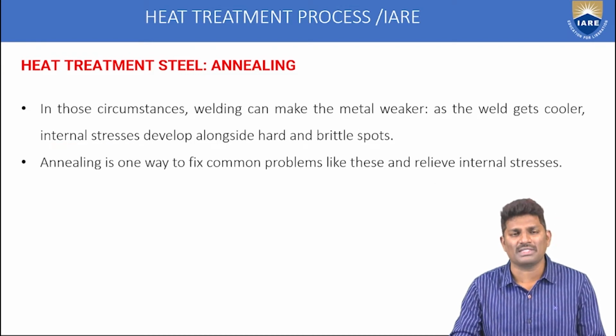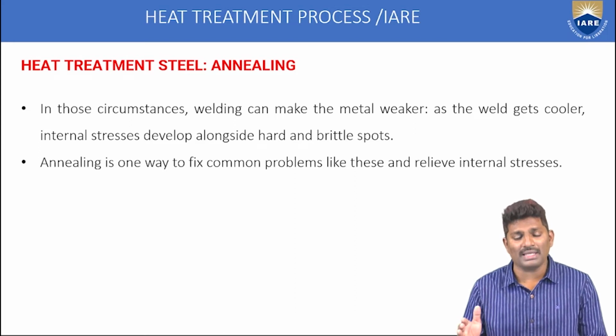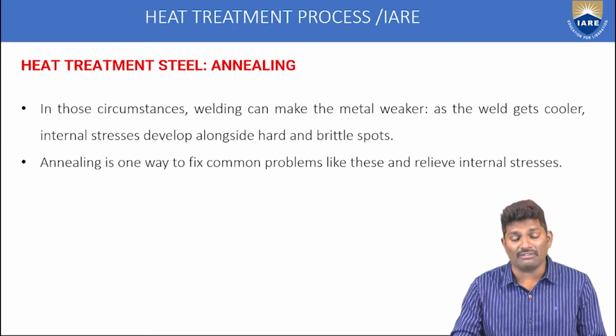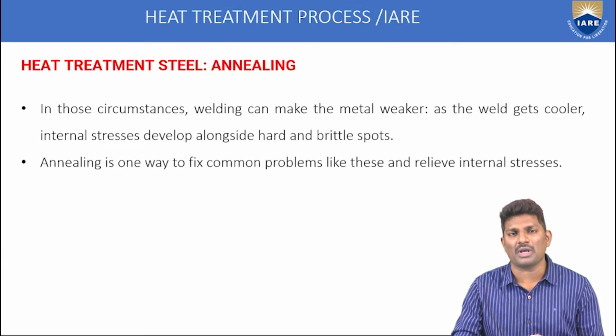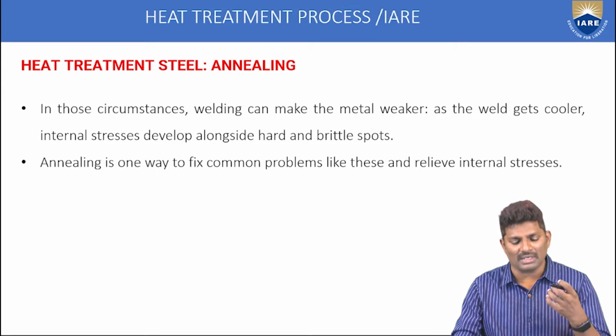And in those circumstances, what is happening? Welding can make the metal weaker. So if you're not giving a proper preheat to the metal before the welding process, what is happening? The weld area, wherever you're doing the weld, gets weaker in nature.